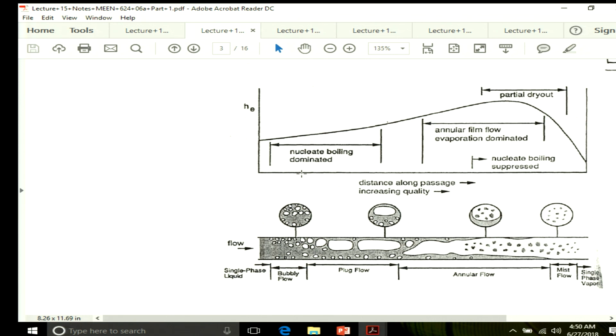Okay. So, if you go by Reynolds analogy, what does the Chilton-Colburn analogy tell you? Do you all remember what was the Reynolds analogy or Chilton-Colburn analogy? Okay. So, what Reynolds analogy tells you is, well, I will come to that in a minute, but the philosophical implication of Chilton-Colburn analogy is, if you increase your shear or pressure drop, your heat transfer has to go up, or if you increase heat transfer, your pressure drop has to go up.